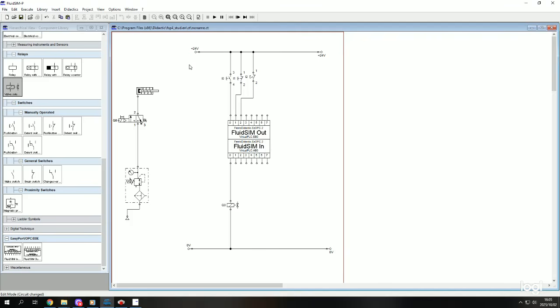Okay, exercise 2 reads as follows. Packages will be diverted from one conveyor to another by means of a diverter. The diverting gate is advanced when the start button is activated and when the cylinder is in retracted end position. So meaning that we are told that it should be at a retracted end position, we need to introduce a sensor, a proximity sensor that will sense the retracted end position before we start.